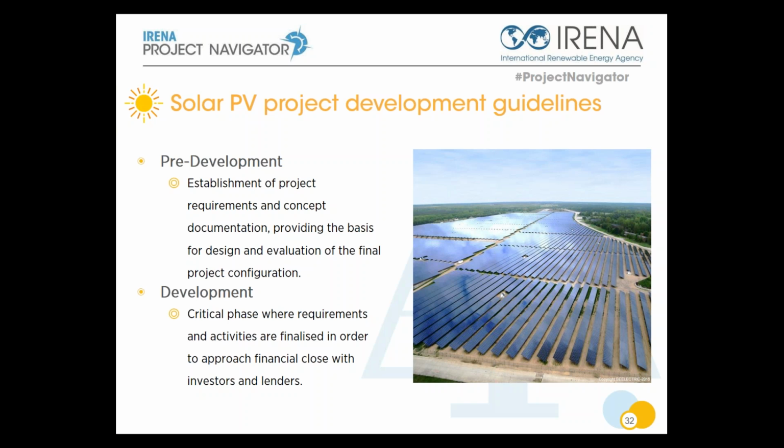Just a few nuggets on this pre-development. For example, in the technology evaluation, we look at the degradation factors of solar PV modules. Traditional crystalline modules have different degradation factors because they suffer power losses like delamination of layers, failures in cell interconnection, or water intrusion.